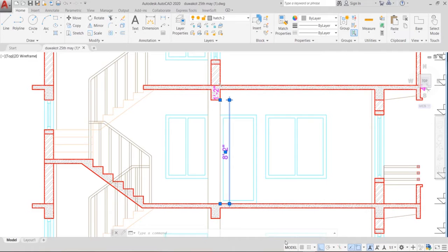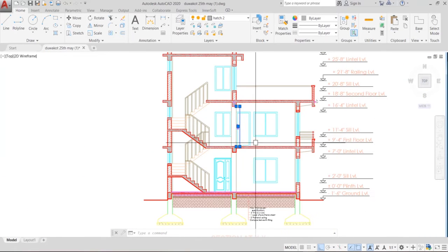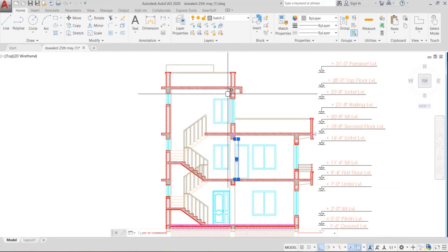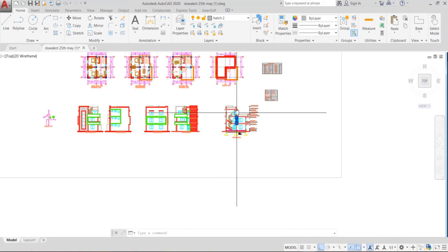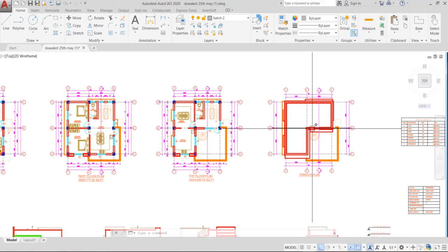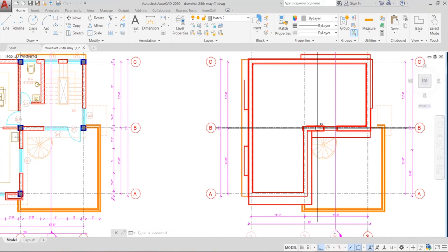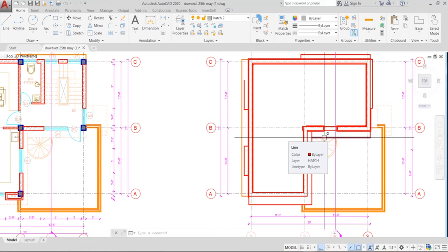And on the third floor, interestingly, we calculated the load on this second floor. The column here has got the balcony, right? So this column here has got only the load coming from this side, but not from this side. So you can either deduct this portion, this area, or it won't make much difference in the load calculations or the size of the column calculation, so we will not reduce this one.